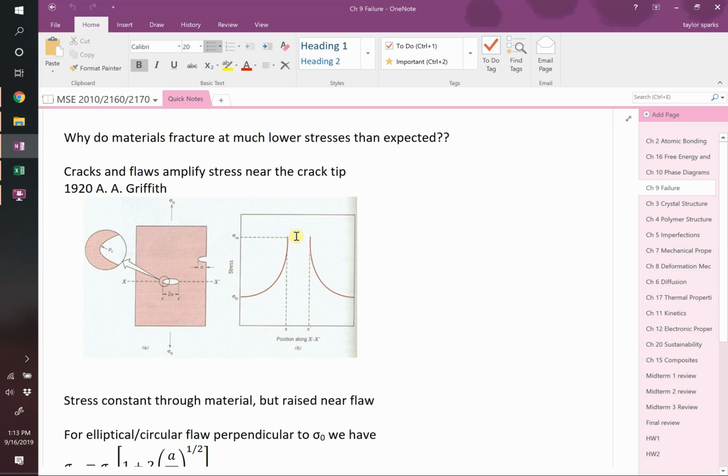Okay, so let's say you've got a pore. Make it sort of an ellipsoid, and the shape matters here. But let's assume that it has some sort of shape, and it has a distance from end to end, which we're going to call 2a. Why do they call it 2a? Because the thing that matters, as we'll learn in a minute, is the half crack length. If it was cut in half, how long would it be? 1a. But there's two of those, so we call it 2a.